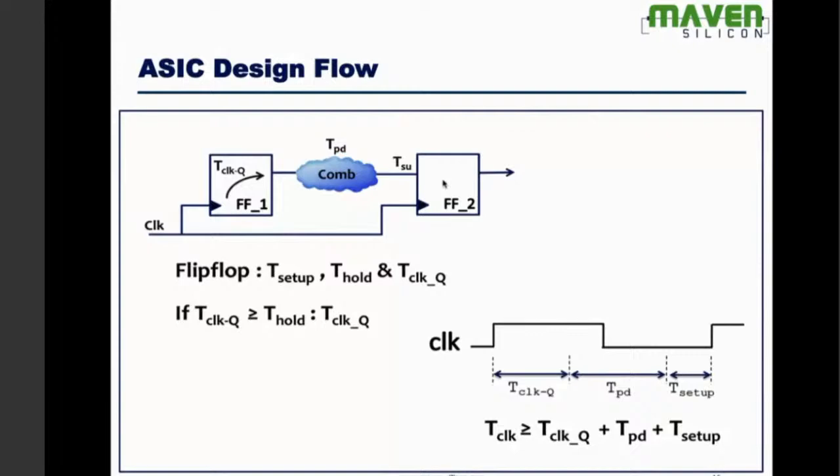When it comes to synthesizable model, we look at two things: how much area it's going to consume, and the clock frequency, at what speed the design is going to operate. So to calculate the frequency comfortably, we follow this design structure.